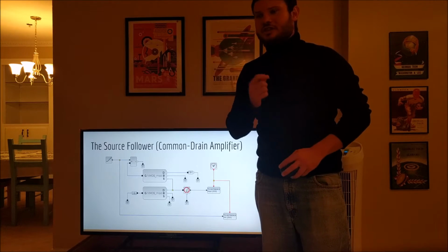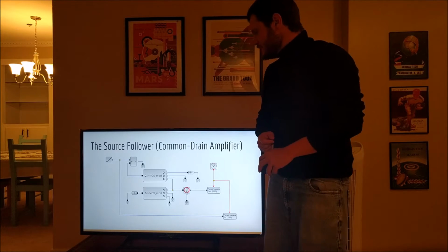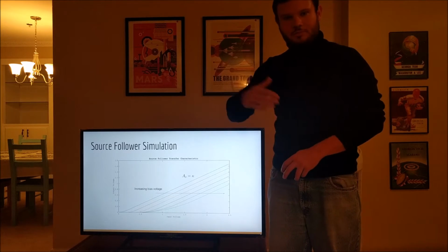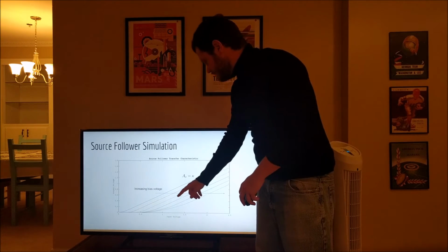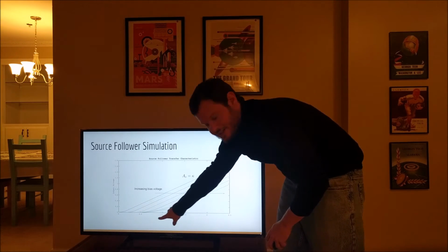If this transistor is in saturation, the voltage gain to the output will be approximately kappa, as demonstrated in this plot, which is output voltage versus input voltage of the previous circuit. When the input voltage reaches about 0.5 millivolts, we start to see some funny effects in the voltage gain here.